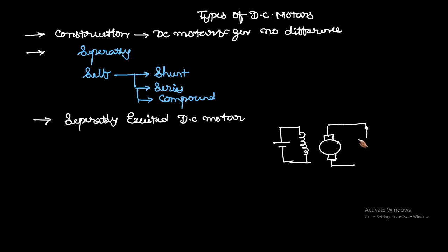We give the electrical energy to the DC motor. So first it gives the line current IL, and the same current flows here as IA, and here the field current is IF, and you have a variable source for the field resistance. Inside this we have the back EMF, and here the terminal voltage is applied. So let us write the equations.